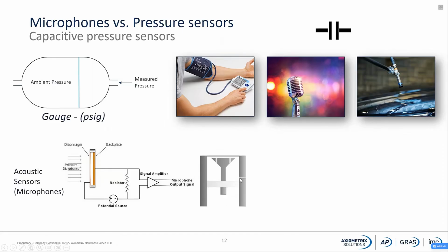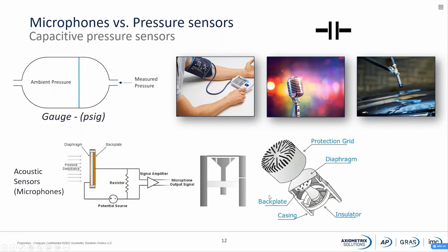You also see a small air gap here, and this is of course the ambient pressure coming in, because if you don't have the ambient pressure coming in on one side of the membrane, you can't really do a gauged measurement. Then it is more a sealed reference measurement, because then you have a sealed area in here with some kind of a pressure. So therefore it is quite important to have this ventilation hole on a microphone.